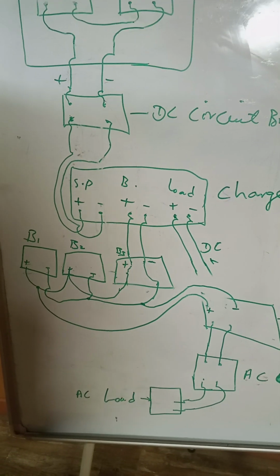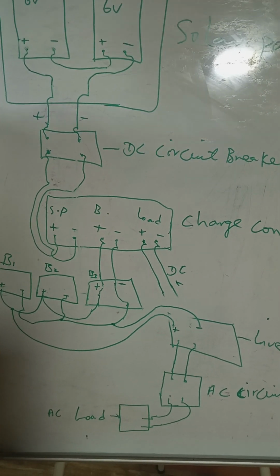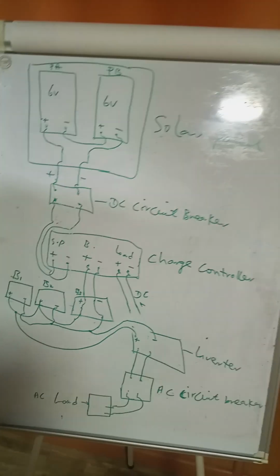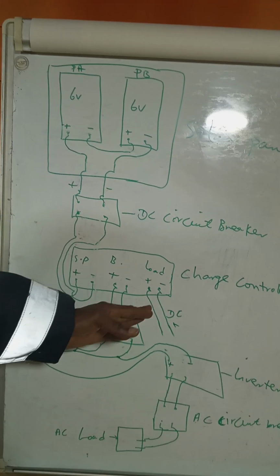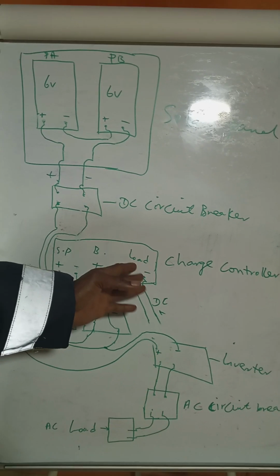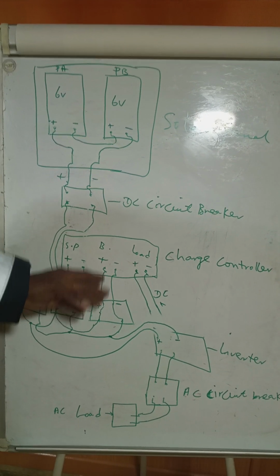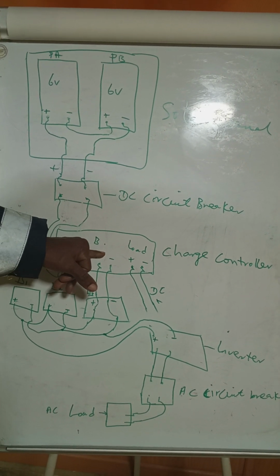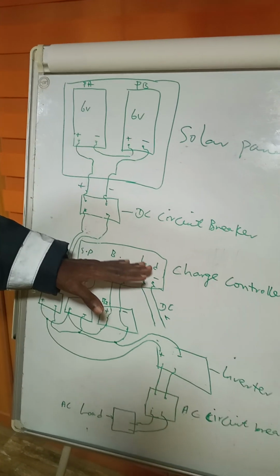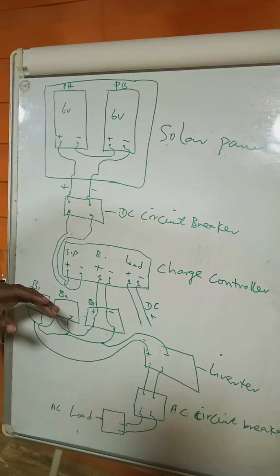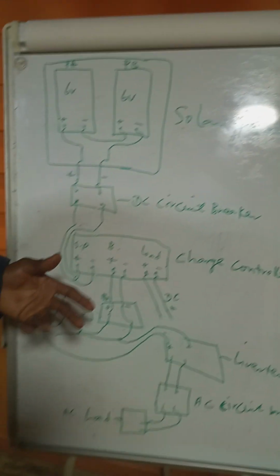Okay, this point I'm going to explain now is very, very important. In some cases, what we do practically in the field is, since this charge controller is an electronics component, if you connect the load terminal of the charge controller to the inverter and at the same time connect the battery terminal of your charge controller to your batteries, there's tendency the charge controller will spoil very soon. Within a short period of time, you may notice that its efficiency has dropped.